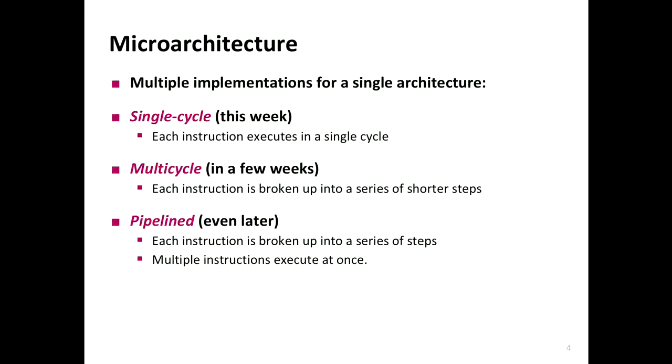So in a single cycle architecture, all these processes happen in one clock cycle. Every instruction executes in one cycle, the next cycle comes in, and you have the second instruction. The bottleneck is that the slowest instruction to execute in the processor will define your clock speed.